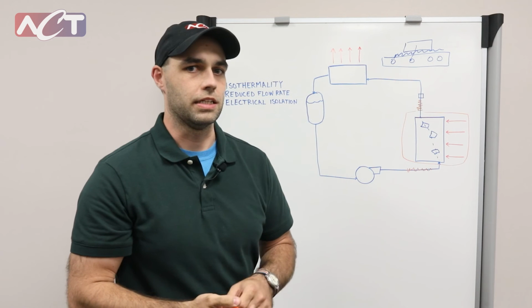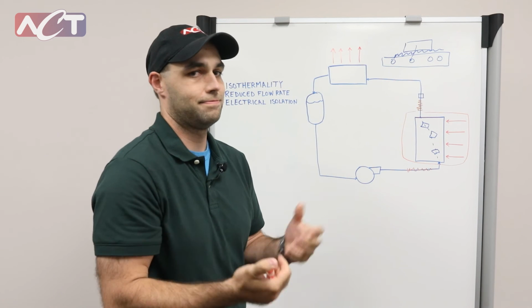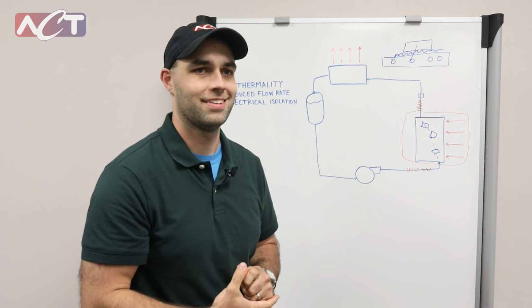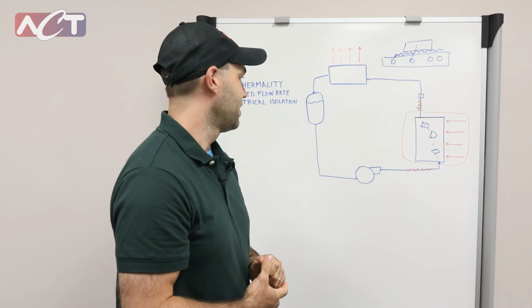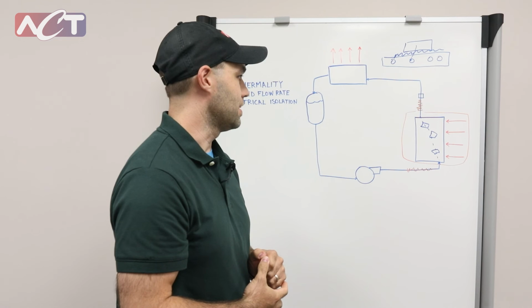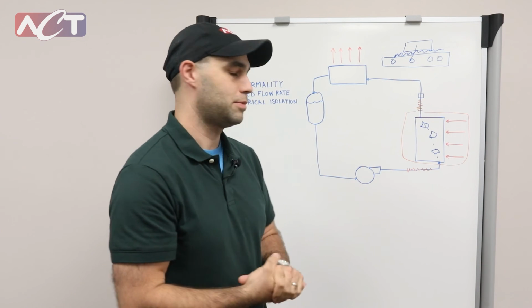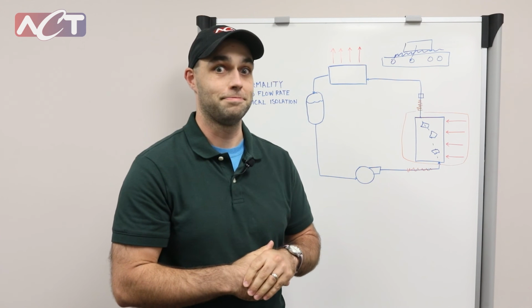If you would spring a leak as well, the fluid is going to evaporate. It's not going to throw water on your electronics, which is another benefit as well. So those are the primary benefits of pump two-phase over single-phase.